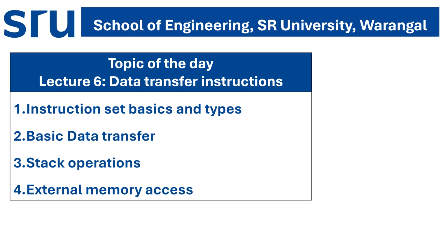First of all, basic data transfer instructions. We will learn how data is transferred between registers, memories, and input-output ports using instructions like MOV, MOVX, and MOVC. We have already discussed the MOV instruction. MOVX, we are using the X term here, this is for external interfacing, external data transferring, right? And MOVC, that is for the ROM.